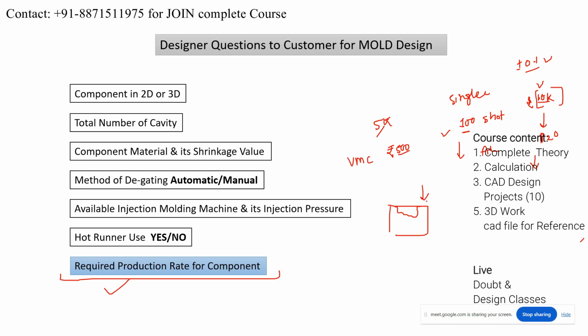So for machining the aluminum, it needs only 1 hour, for example. For MS, creating the same cavity will take 3 hours, for example, and for the P20, it will take around 8 hours. So multiply by 500 for all. Only 500 rupees for the aluminum manufacturing cost, right?